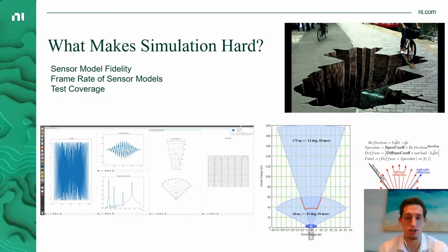So if you imagine the energy you take to put into a high fidelity sensor to incorporate that physics, to incorporate that validation of that sensor, and any errors and noise that are associated with that sensor, well, that usually requires a whole lot of complexity in computation. So your simulation systems may be 10 computers, 20 computers, 30 computers deep of high performance processing in order to get these images and these frames generated in real time that can then stress your system in real time. So you have this battle of fidelity versus computational excellence of your system. A lot of the high performance, high fidelity sensor simulation systems that we've seen require many, many computers to actually accurately model these sensors and to do that in real time.